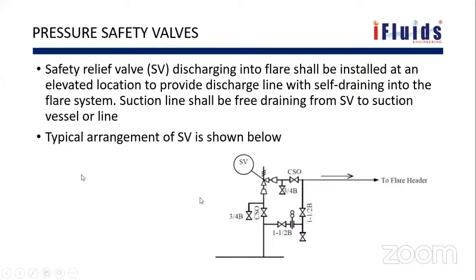Safety relief valves, pressure safety valves. In case of any over pressurization, they will relieve the excess pressure to protect the equipment, to the flare header. So this is how a PSV is shown. You see from this line, this may be a line or an equipment.